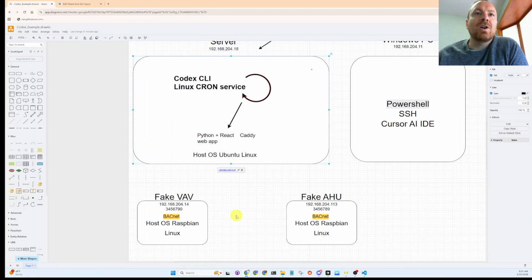So in building automation systems, usually if this was a real building, there'd be an outside air temperature sensor, typically hardwired to a boiler, and then a supervisory level device always shares that data from one device to the next.